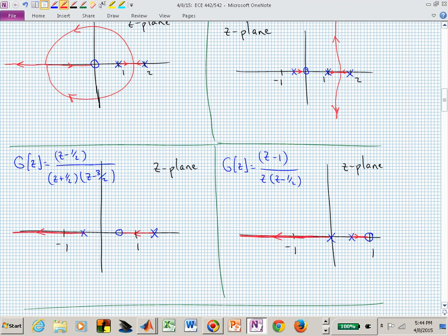That particular problem, you would have to check to see if it's even stabilizable. My guess is it may not be. Because as you're cranking up the gain to move that pole at 3/2 into the unit circle, you're also moving that pole that's in the unit circle possibly outside the unit circle.